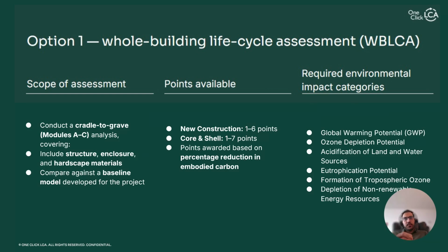And we are going to let you know what the features of this baseline are, but generally this baseline could be the first draft of your design. If it's an early stage or you don't have any data, that you don't have a first draft, you can use another tool from One Click LCA, which is Carbon Designer 3D, that is going to simply, by knowing just the type of the building, office, educational or anything else, the area of the building and the location of the building, you can easily have your baseline. So no need to go through assessment.